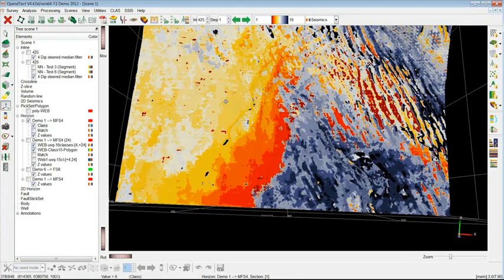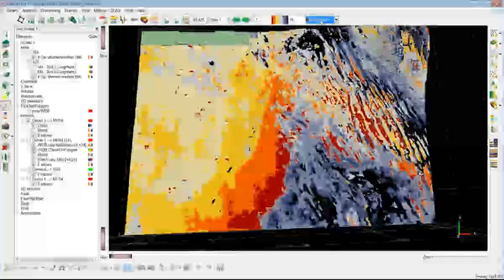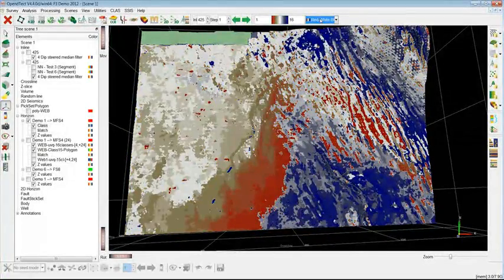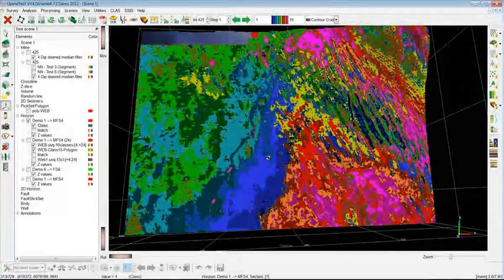So what I will do here, I click here, and I will just scroll in order to find the color bar which will best match my display. I can play around and then display the one which gives me a good display. Let's click, for instance, this contour gradient, because the contour gradient uses a contrast, so the colors are really separated.